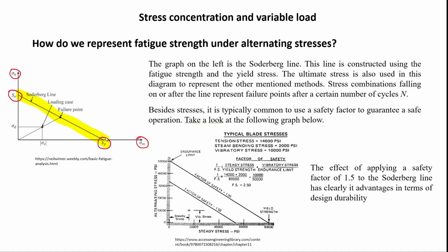Okay? Meaning that, to make it very simple, whatever loading case you have that falls within this line is going to be okay. And additionally, if we have a point like the one presented here, this is the loading case of your application, the distance between this parallel line and this one here is going to be your safety factor.